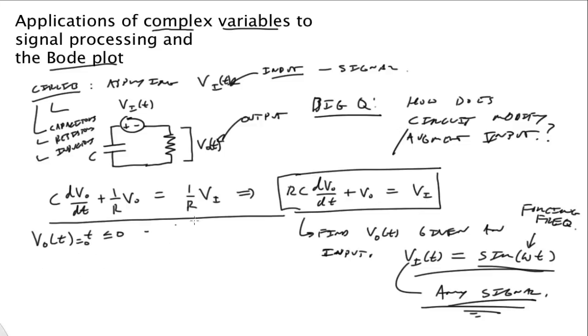So let's not think about any kind of initial condition that might foul things up. When we do that, we can also define RC as what we'll call the time constant of the system, which is related to the capacitance and the resistor. We can also define it as 1 over what we'll call omega naught. This time scale can be thought of as a rate constant as well. That represents sort of an optimal rate for this system, so we can call this a characteristic constant.